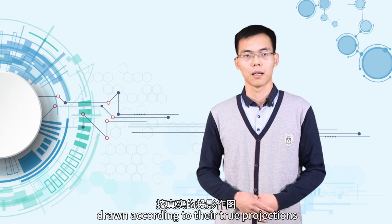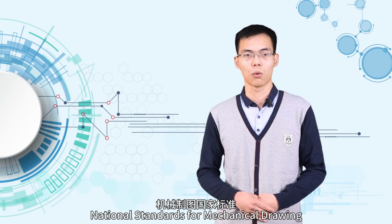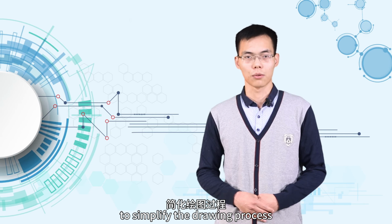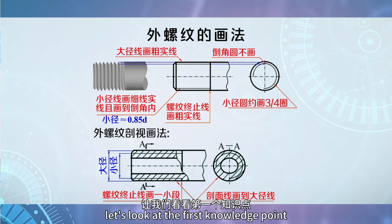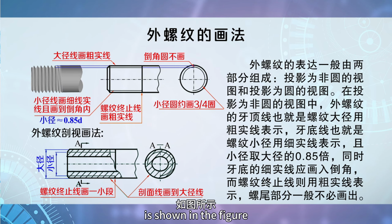Threads are generally not drawn according to their true projections. Instead, we use the drawing methods specified in the National Standards for Mechanical Drawing to simplify the drawing process. Let's look at the first knowledge point. The drawing method for external threads is shown in the figure.